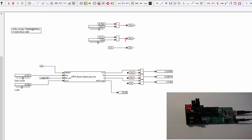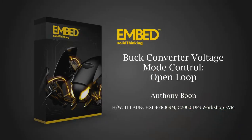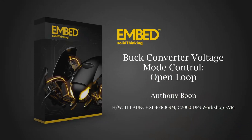What we're doing up here is we can trim the voltage. Obviously this is running fast. We can make these get slower. I wanted to check this, but we can move this up to the voltage that we desire, and we can check it on the hardware itself. We've got 3.31 volts here, so the trimming is good. Same with the input voltage. We can use this trimming in a closed loop diagram, which we'll attempt to do next. So see you then.